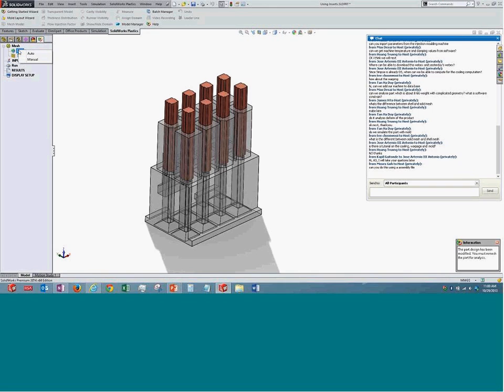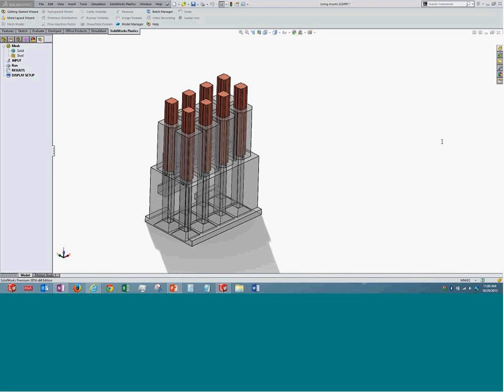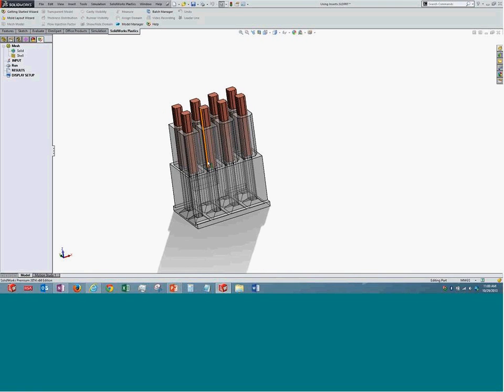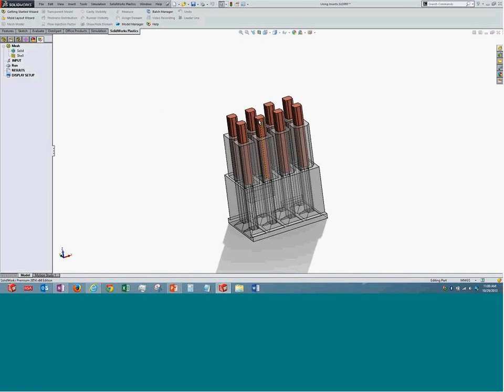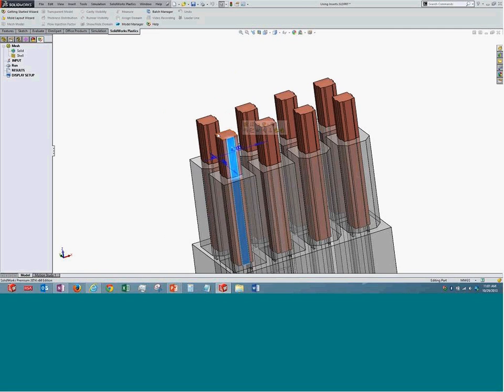Let's move on to this last example which I'm going to show today. It is on insert overmolding, wherein the V component and all these colored things are components which are present in the plastic part, and the rest of the transparent part is the actual plastic part where plastic is going to be filled. So it's going to move around this set of copper components and encompass them with plastic. That's how we do this.